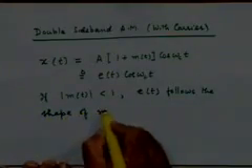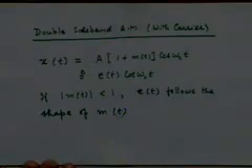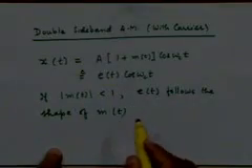But wasn't that always the case? No. In the DSB-SC case, the envelope is proportional to the modulus of m(t). What we would like to have is the envelope be proportional to m(t) itself. And of course, why we would like to have that is another issue, which I will come to in a few minutes. How does it help us is something that we have to still discuss, but I just want to point out this interesting fact which was not available to us in the suppressed carrier modulation, because there the envelope was proportional to the modulus of m(t). Here we are making the envelope proportional to m(t), right?